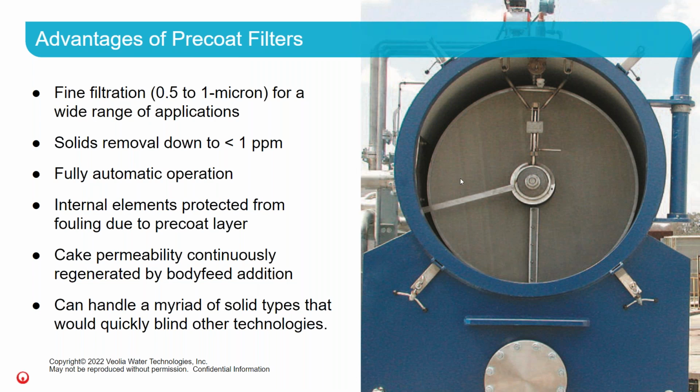So if you do need to get a longer runtime, Precoat filters with the addition of body feed, you can achieve that. And with all of this, you can see how the Precoat filters can handle a wide range of applications and different types of solids that would otherwise quickly blind other filters.